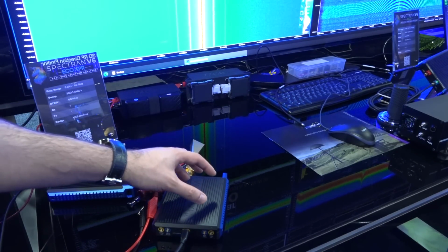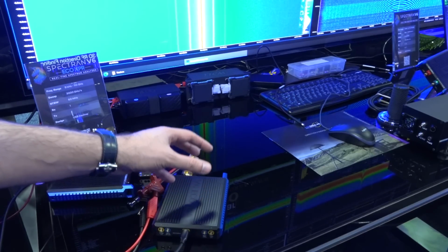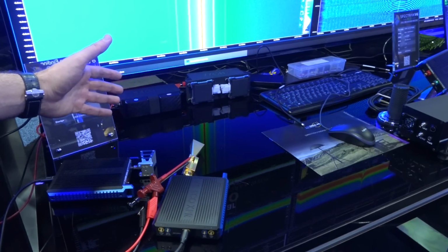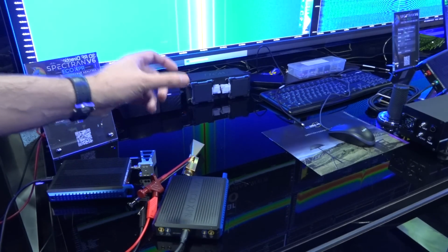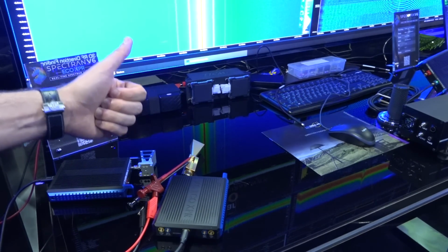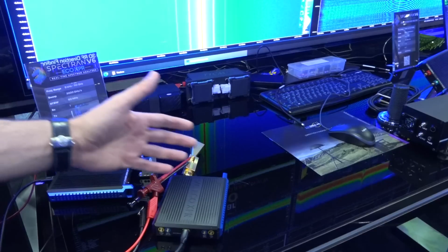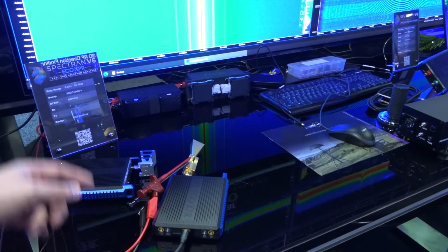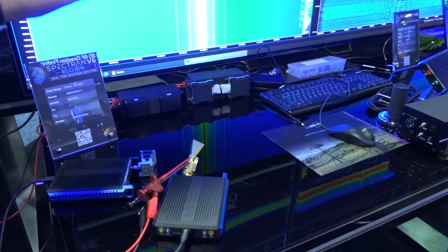I mean, consider for a moment what this implies. It means that you can look at spectrum from 9 kilohertz to 110 gigahertz, everything that's over the air, and gaplessly pick the frequency you want, 490 megahertz, transmit it, record it, save it, and process it, all with rapid switching between the frequencies. I don't think there's anything like this on the market. And we'll talk about the software in a second, because that's a whole other domain.